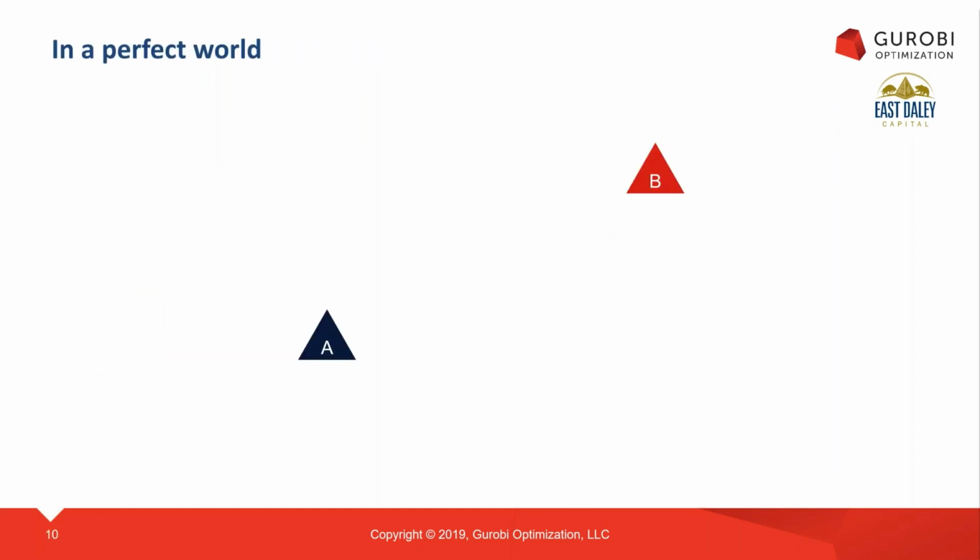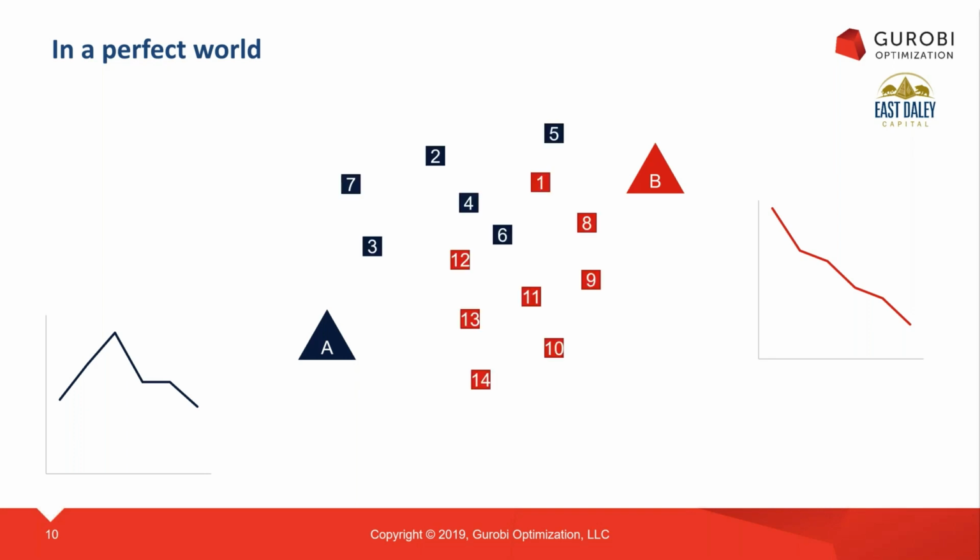Okay, so in a perfect world, we want to understand risk on this natural gas supply chain. So we want to understand exactly how it operates. We know that there are two processing systems, A and B. We might know the throughputs of those systems. It would be nice to know what the throughput looks like on each system, because the throughput is directly related to what they can feed into the connected NGL pipelines and the residue gas. And we'd love to know which wells are feeding those systems. So if I know that wells 2, 4, 5, 6, 7, and 3 are feeding processing plant A, when I forecast the volumes for those individual wells, I then know what the forecast looks like for the plant, and then I can forecast pipelines and propagate all those changes throughout the supply chain.